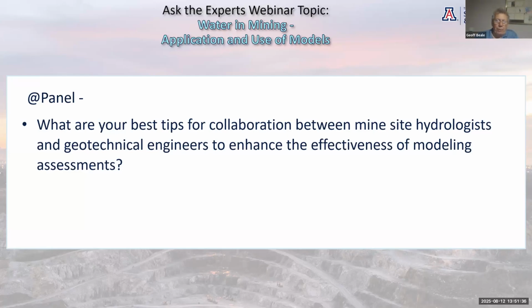So just make sure you understand what you're dealing with in terms of what might fail, where the structures are, to make sure that the field instruments are focused on those, for both the hydro and the geotech. One of the things we do a lot more of these days is put piezometers, TDRs, shape arrays, and inclinometers all in the same hole. So putting in joint holes is a good way to get collaboration.